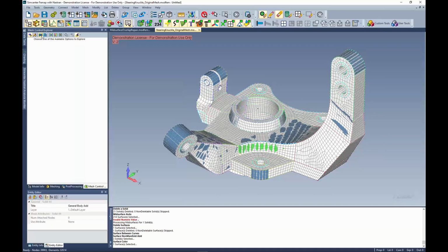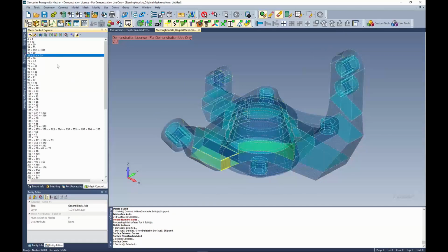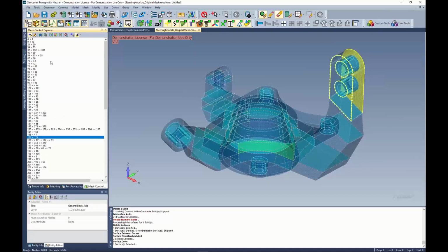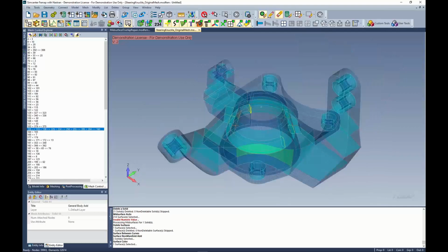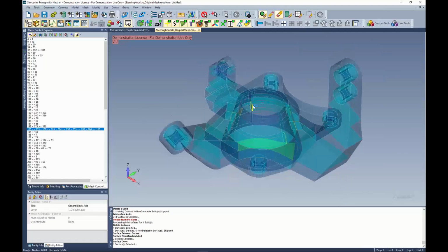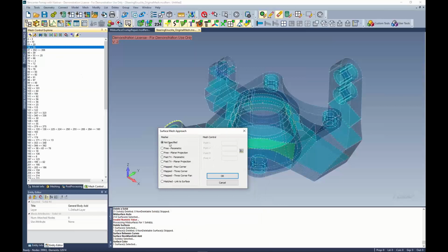Let's go into the surfaces that are all paired together. So this pulls in a list of all the paired surfaces, and I don't think you have to do all these pairings manually. There's definitely a way to automatically do this, but the new functionality is you can see which ones are paired together in the table, and you can pick and choose which ones to show. So it's actually really cool because you can, for example, choose these, right click, and you can change the meshing approach if you need to.